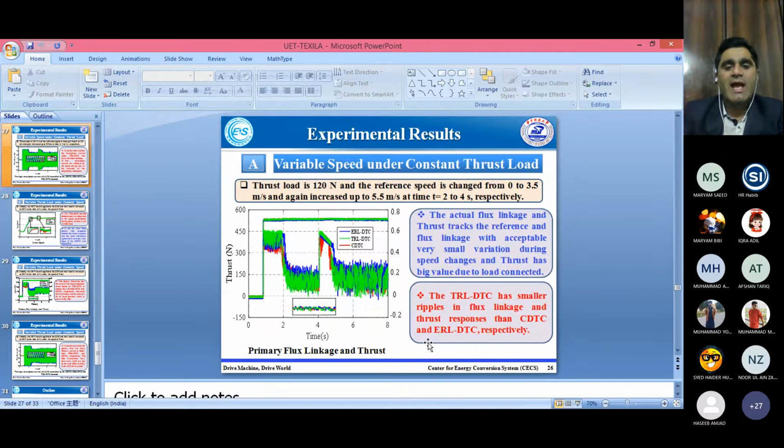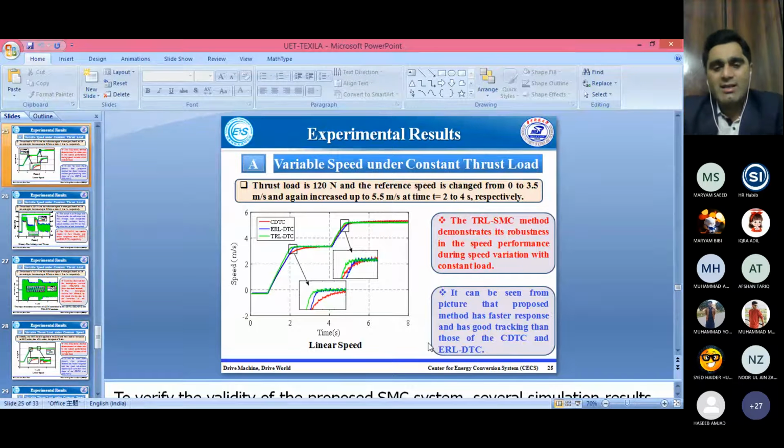Yes. Actually slide mode control is faster than the conventional PI control methods. But it has one disadvantage, which is chattering. Chattering is observed with slide mode control, which is an inherent problem of slide mode control. But now researchers have done research and say that by using an appropriate slide mode control or reaching law, you can eliminate this chattering phenomenon from the slide mode control, like super twisting, like second order slide mode control.